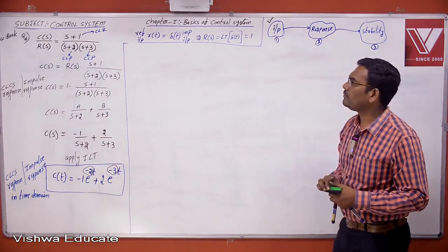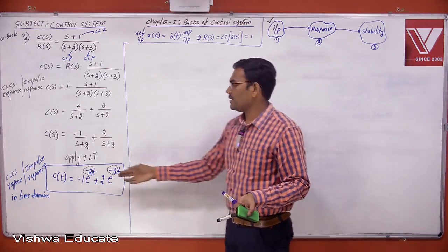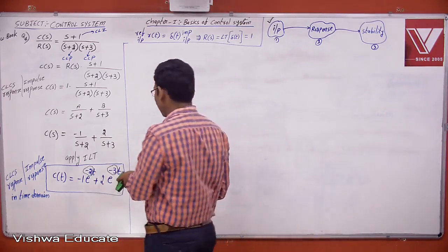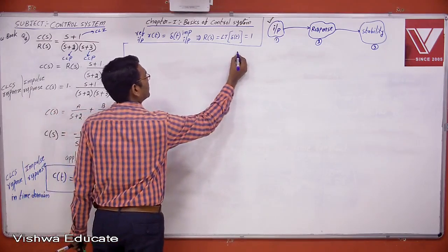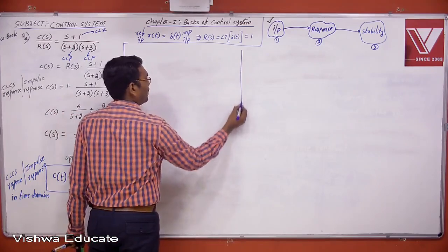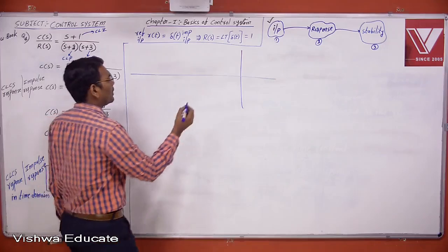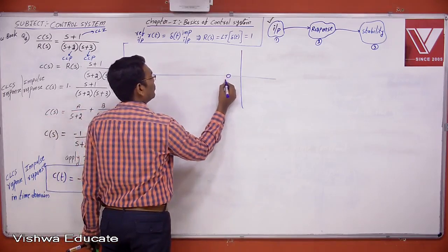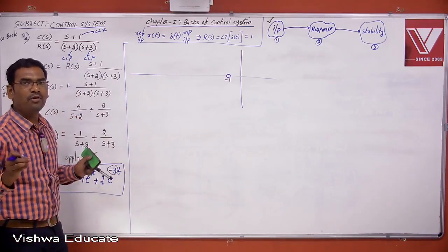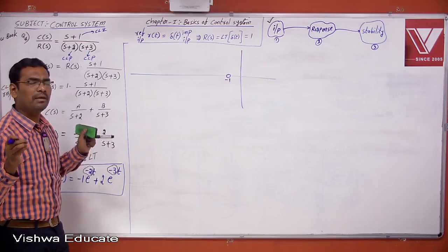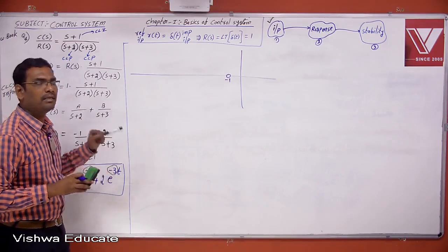Right. Now this is the response in time domain. Then we want to draw the response. Yes, we will try to draw the response. Before we draw the response, one important point has to be identified. This is one closed loop zero. From this problem you want to understand that the complete system behavior depends only on the poles location but not the zeros location.